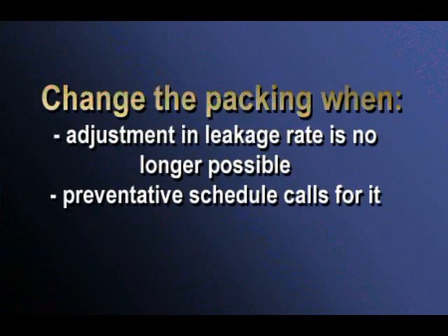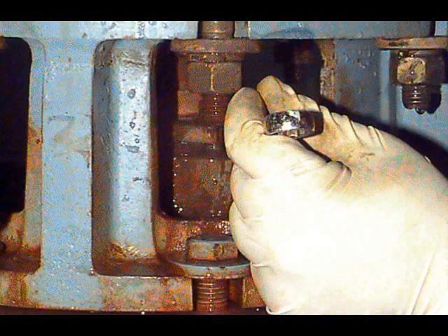Note that packing is also changed as part of scheduled preventive maintenance. Normally, packing is changed at regular intervals or after a certain number of hours of pumping. This avoids the possibility of old packing becoming hard and scoring the shaft, even though a proper leakage rate can still be obtained. Packing is designed to wear, and it will deteriorate with time.